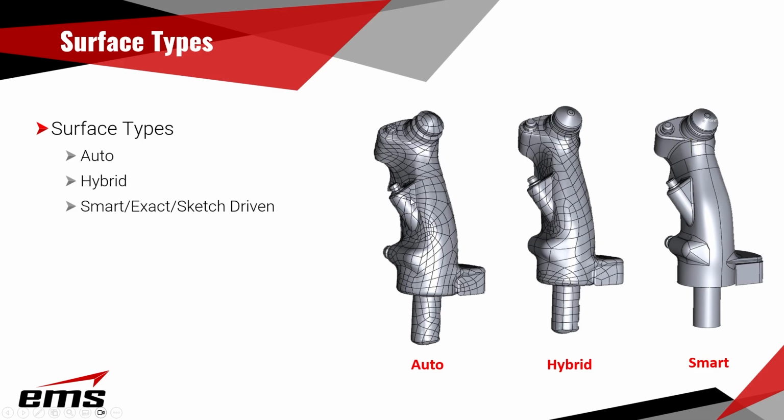Now, one big difference between polygons is they are triangles. At least the way we refer to a polygon, they are three-sided entities from a 3D scanner. You'll notice these are all four-sided. All surfaces must have four sides. So what it basically does is build these mathematical surfaces through the scan data as four-sided surfaces. Now, the auto surface, and we're going to go interactively here in a minute, is an exact copy of your scan data. There's no difference. It is an exact copy. It's just now as a surface model.